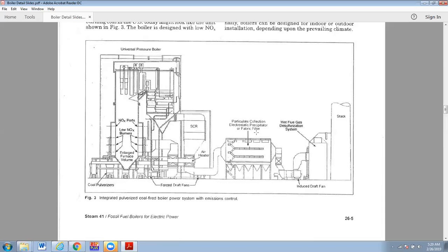So, taking the voltage off of the system, shutting down the circuit briefly, wrapping the electrodes for the ash to fall off, and then turning that back on and moving to a different section. In the SCR, it's creating some additional particulates by chemical reaction to reduce the amount of NOx in there, and so some of that gets captured by the precipitator as well.